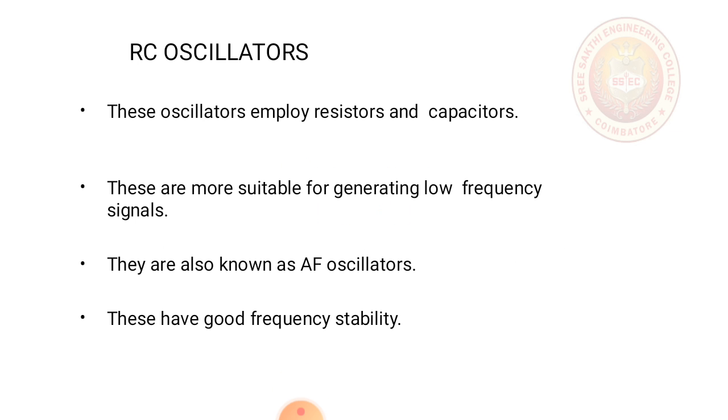RC oscillators. These oscillators employ resistors and capacitors, thus the name RC oscillators. These are most suitable for generating low frequency signals, also known as AF oscillators, that is audio frequency oscillators. These oscillators have very good frequency stability.